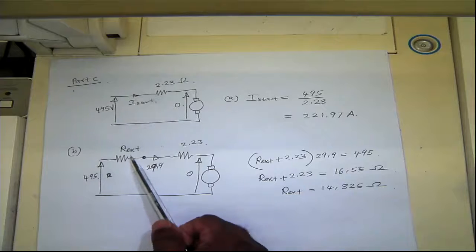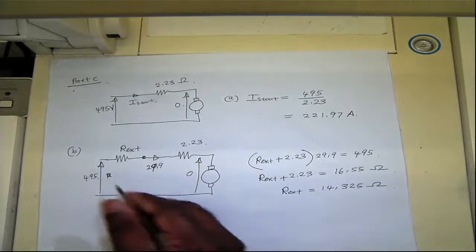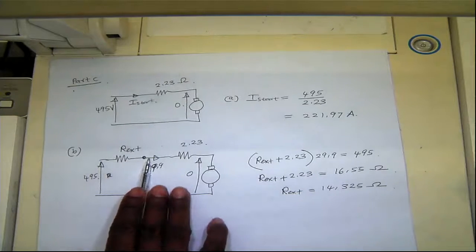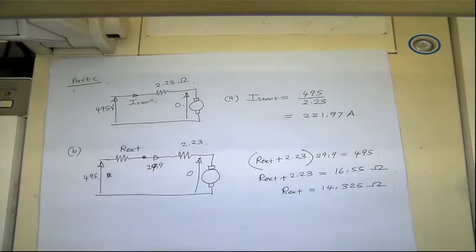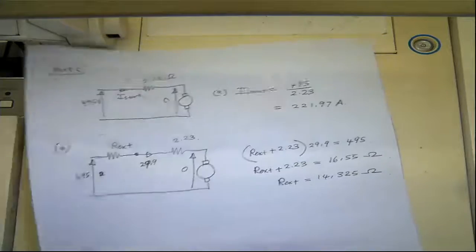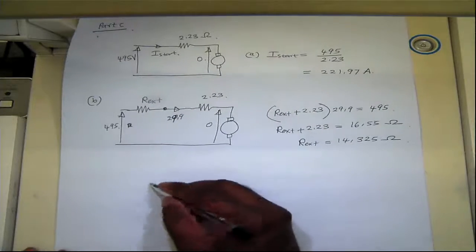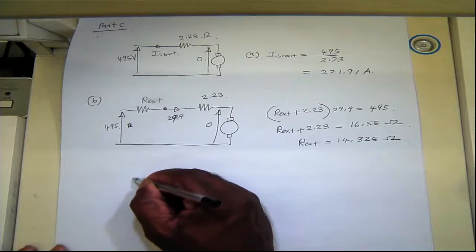At some point you need to disconnect this, but if you disconnect it and apply full voltage, you'll still have a huge voltage drop across the resistance, and the current will probably exceed the rated value. So one of the starting methods is a cascaded arrangement of resistors, so that when the speed increases, it steps through the resistors. Instead of one resistor, you have a series of resistors.